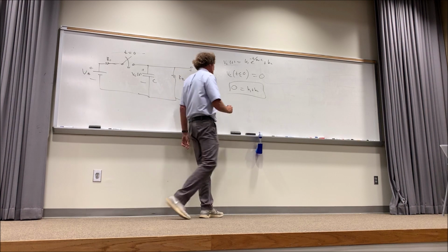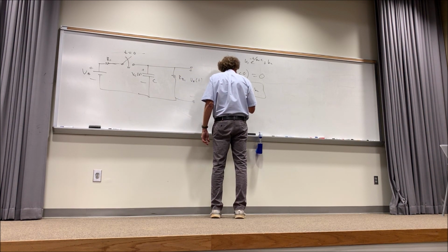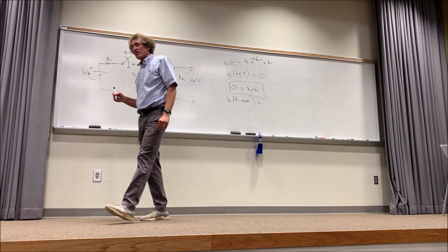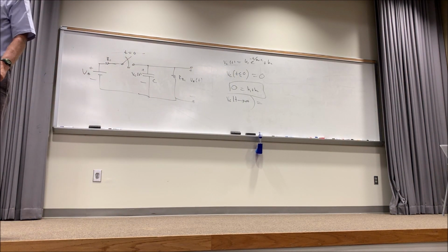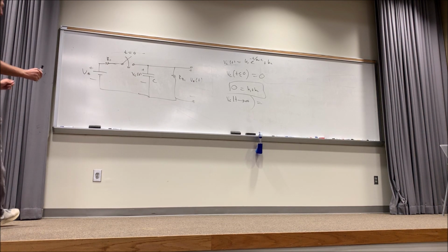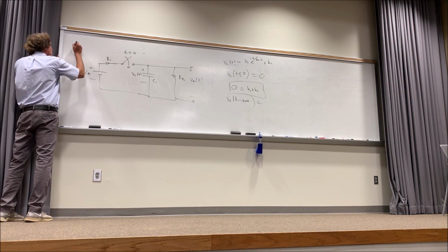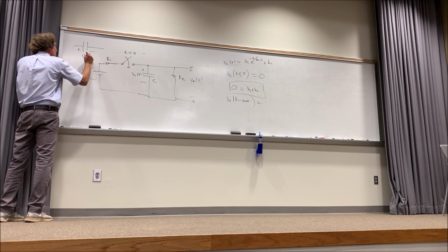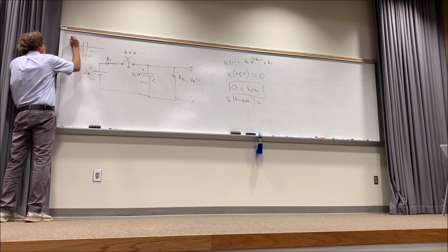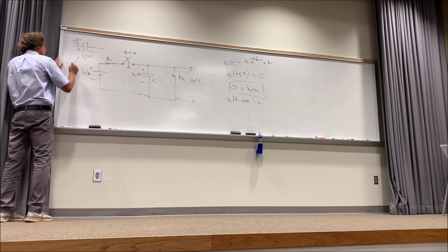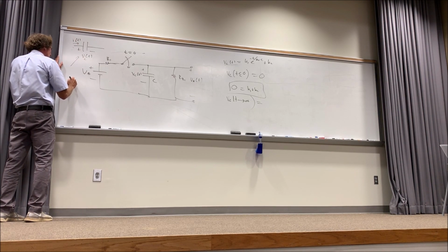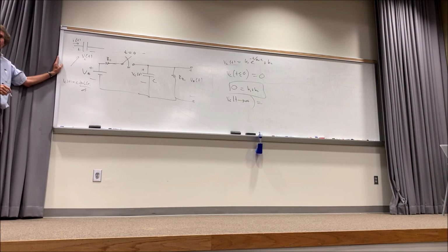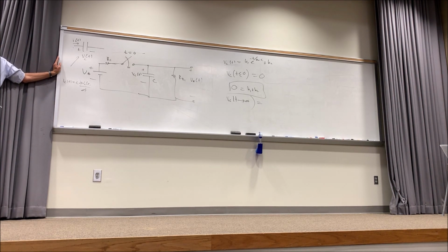Now we find the voltage Vc as t goes to infinity. And here, I have to tell you something. I want the voltage across the capacitor as time goes to infinity. Please listen. Remember the equation for current through a capacitor. In general, you had plus to minus Vc of t, and a current I of t going in, and the relationship there was Ic of t is equal to C times dVc of t over dt, right? I'm stating it explicitly for a reason.